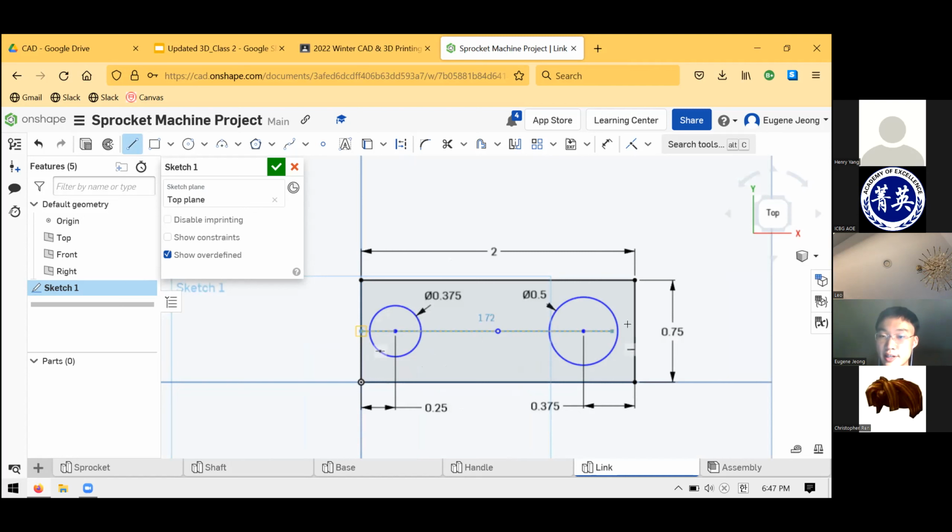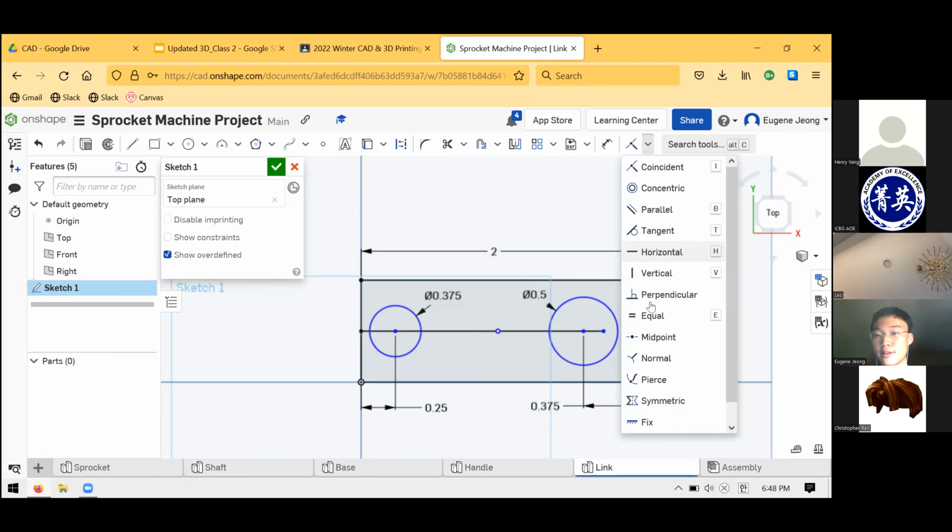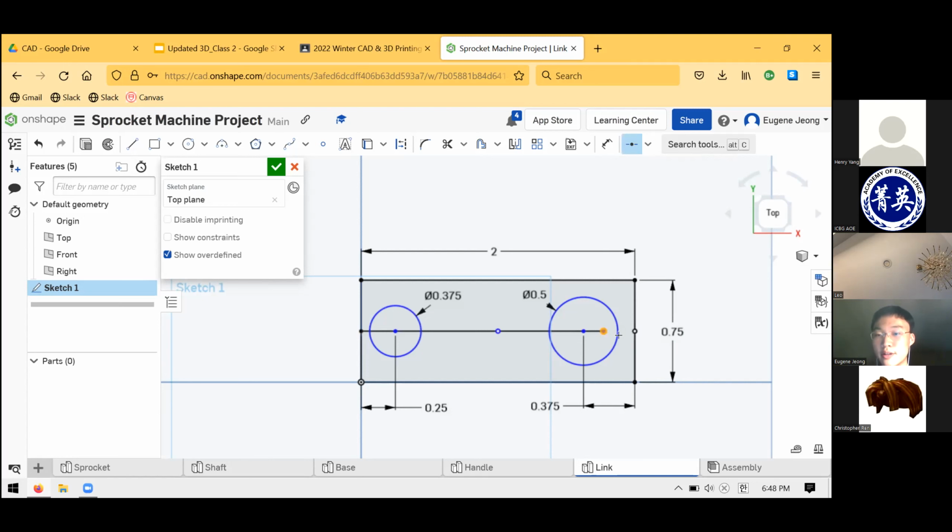And again, on the other side, to automatically create that midpoint relation, I click on that little square on the other side. You have to be pretty careful about it. And if it doesn't show up, you can always manually create those relations using what we know about creating relations. So I would just do the midpoint relation, click this point, click this line, and it would work.